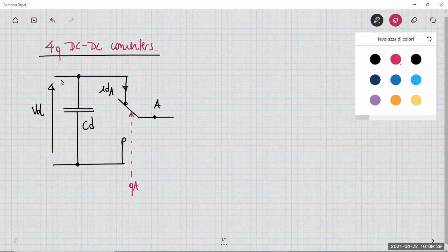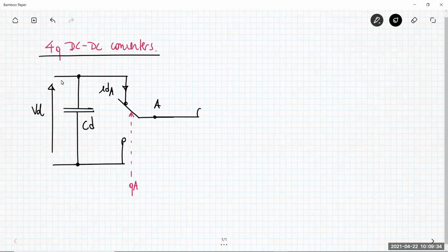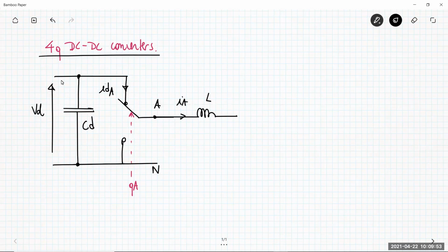As you will know, this switching power pole with the inductance assures the bidirectionality of the current flowing here, the current IA, but the voltage at the output between the node A and N is just positive voltage. In order to make the voltage reversible, I have to add in parallel another switching power pole. So let me put here another two-position switch this way.